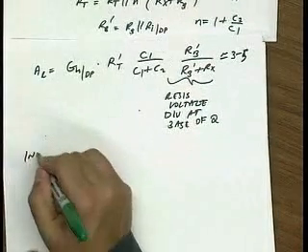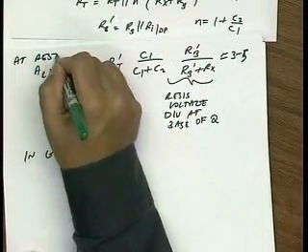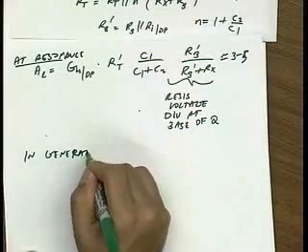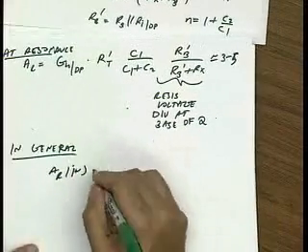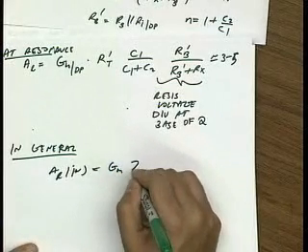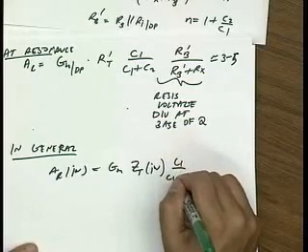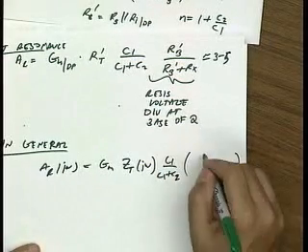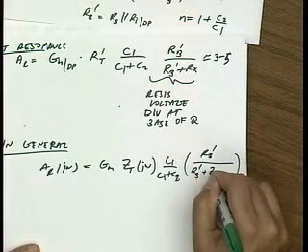But in general, as we move away from resonance, so this is at resonance, the loop gain as a function of frequency is the same GM, same tank impedance, same feedback factor, times now a function that is very strongly dependent on the crystal.